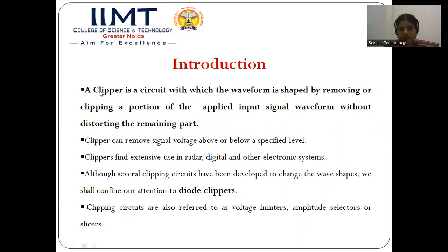So, what is the purpose or function of the clipper circuit? A clipper is a circuit with which the waveform is shaped by removing or clipping a portion of the applied input signal waveform without distorting the remaining part. As the name suggests, a clipper clips out or removes a certain portion of the applied input signal waveform without disturbing the remaining part of the waveform.